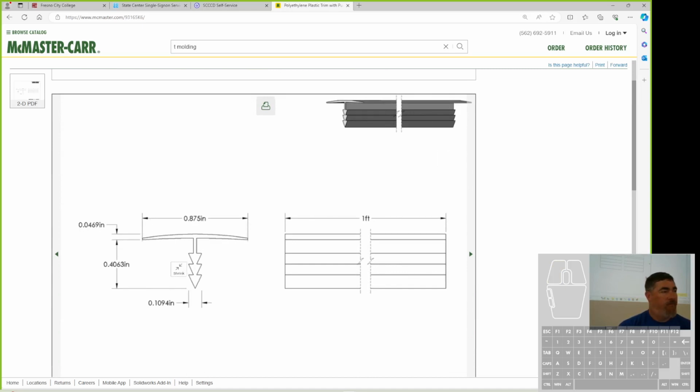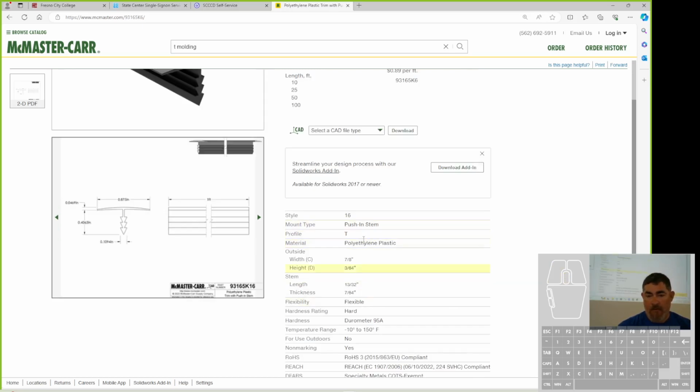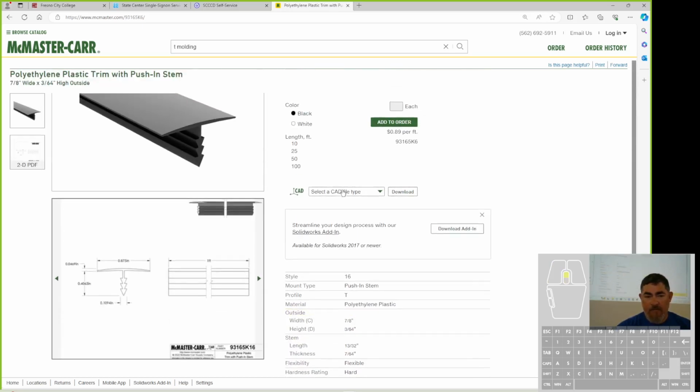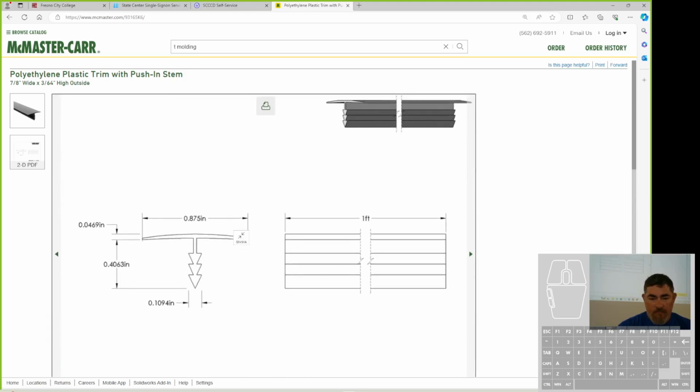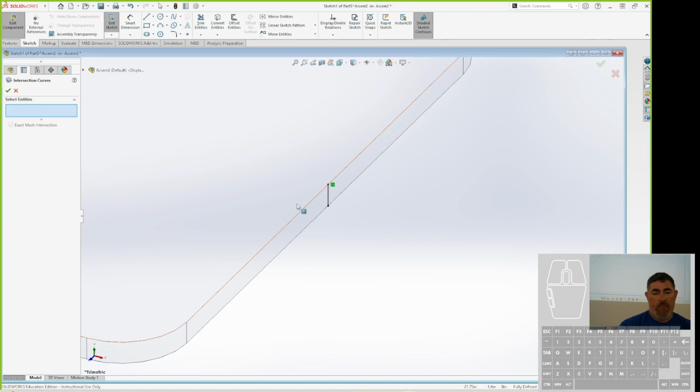But also for the groove on the tabletop, I need to make it that big, right? So does it tell me the size? No. So probably make it a little bit smaller than this, so that way you can squeeze in there. And at least that deep. So probably make it just 1/2 inch deep, or 0.4375. So is that 7/16? Yeah. Probably make it 7/16 deep in that. But I can add that in later. But I'm going to make it here.